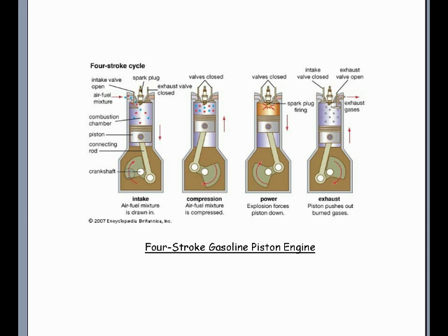The crankshaft is connected to a camshaft which rotates at 1/2 the RPM of the crankshaft. The camshaft's function is to open and close the valves using cam lobes. The maximum rated brake horsepower will be reached at the middle range of RPM on the 4-stroke gasoline piston engine.